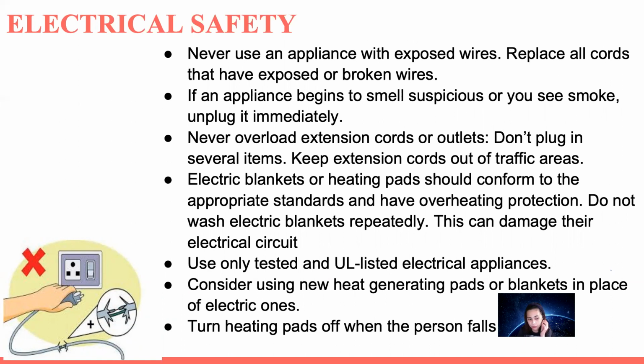You should always buy good quality wires, because you never know if you bought a low-cost one and it will be broken, it can cause fire and electrocution also for you. If an appliance begins to smell suspicious or you see smoke, unplug it immediately. Never overload extension cords or outlets. Electric blankets or heating pads should conform to the appropriate standards and have overheating protection. Use only tested and UL listed electrical appliances.